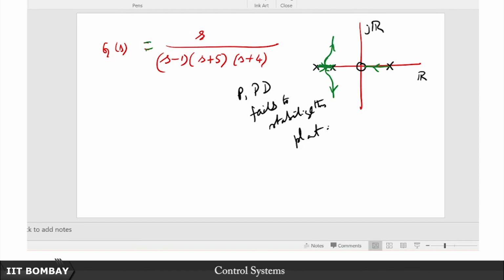Not just that, if you have actually practiced some of those root locus design problems, you would have noticed that there was a bit of trial and error involved, right? Because we said, well, approximate cancellation of the pole and zero, and then we have to simulate and check if the performance is as desired. We might feel that it's approximately cancelling out, but as a matter of fact it may not cancel out as well as we want. So again we start from scratch, and it's a bit of an art after a point. Even though it involves a lot of calculations, it's a bit of an art to design these pole zero locations of the lead or lag compensators. So if I give you some such typical plant, you might find it inordinately difficult to have a satisfactory behavior as well as steady state error and things like that. So that was one restriction, it was laborious.